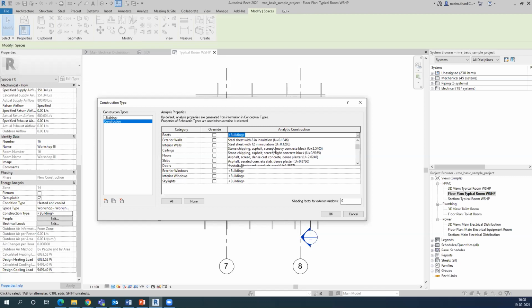We generally consider what material we are using, and one of the most important factors for the building material is the R value, which is inversely proportional to the U value. So the R value has a relation with the U value. If we can fine tune the values, it is definitely going to give us the approximate nearest value of heat gains that we are getting. If the architecture model is created and all the values are given in the architecture model, we can utilize those values instead of giving values here.